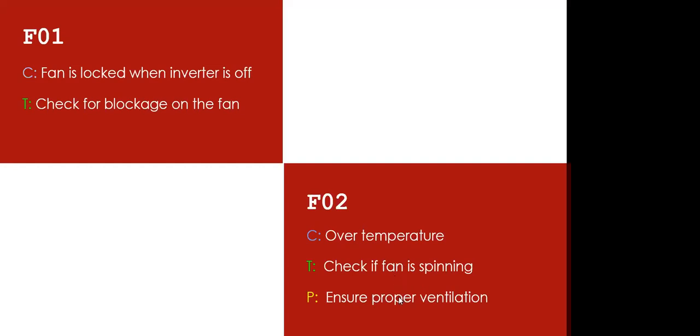We need to make sure that our inverter is well ventilated. Anyone who wants to install the inverter, it must be ventilated. At times, the fan might be rolling, and we still have over temperature, not because of anything else, but because there is no proper ventilation for the inverter. And this might cause damage to the inverter.